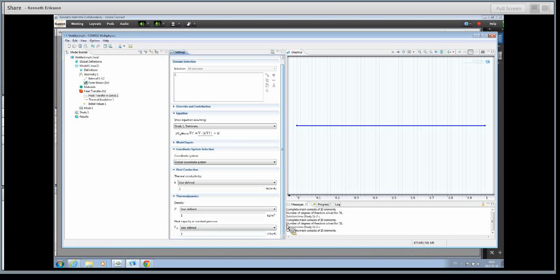We also want to specify U here, which has a default definition of 0. And that is fine, because that is exactly what we want. This term is not present in our case. We already had these two terms. But we have to specify Q, the heat source, and that is not part of the menu here.